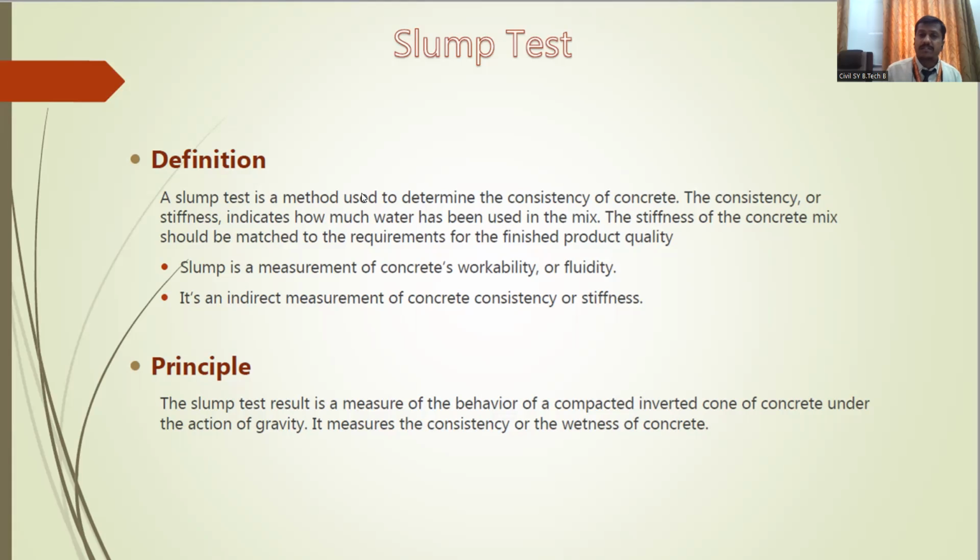Now, what is the slump test? The definition is there in front of you. Slump test is a method that is used to determine the consistency or the workability of the concrete. The consistency or the stiffness indicates how much water you have used to prepare that particular concrete mix.